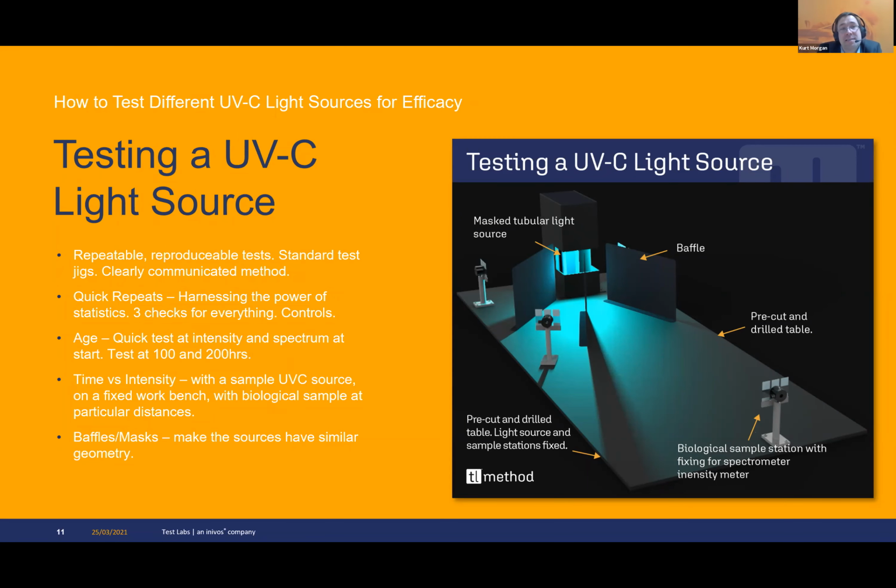And there's the LEDs. The LEDs are about 265 nanometers, so slightly longer wavelength than our fluorescent bulbs that we're used to. What I have seen is people talking about this sort of magical place where UVC light is most effective. Some people talk about 254 nanometers as if it were an effective wavelength. It's just the wavelength that happens to be emitted by mercury fluorescent tubes. Exactly. So it's not a brilliant wavelength, by happenstance.